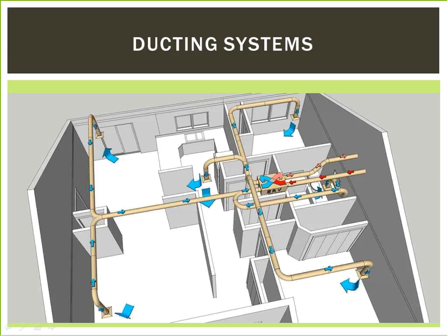As such, designers and installers attempt to keep their installed lengths or runs short, less than 15 feet or so, and to minimize turns. Kinks in flex must be avoided. Some flexible duct markets prefer to avoid using flexible duct on the return air portions of the HVAC systems. However, a flexible duct can tolerate moderate negative pressures.